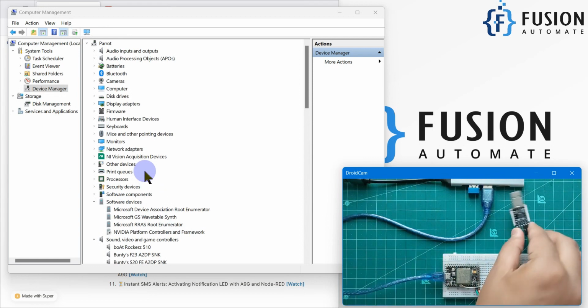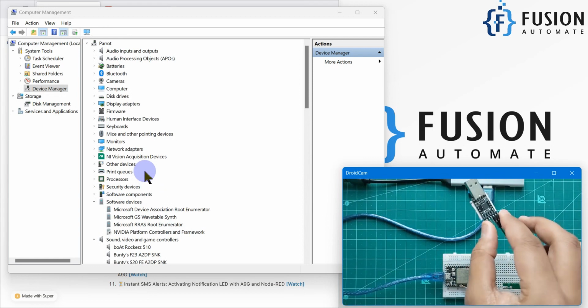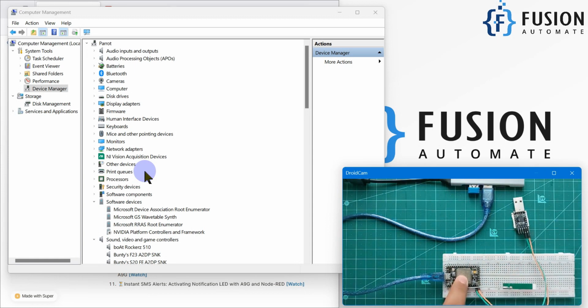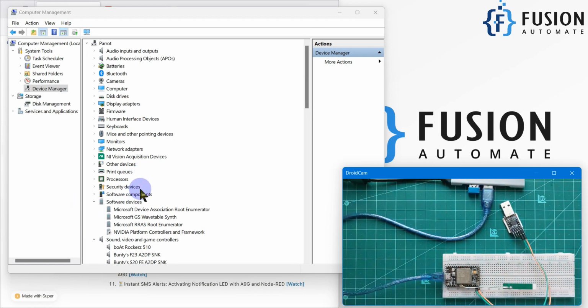This is the USB to serial converter, CP2102, which is the chip inside this. It is connected to this A9G board, and the A9G board is powered using this USB cable. Once you connect this to your system, you will have one COM port in your system. We are going to use that COM port for serial communication between Node-RED and the A9G board.